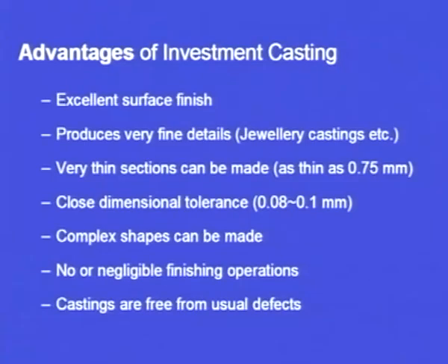These complex details are cast by investment casting. And the next one is very thin sections can be made, of the order 0.75 mm, and we obtain close dimensional tolerance. In the case of the conventional sand casting process, if we want to manufacture a certain component, the final casting that we will be obtaining will be a little larger.